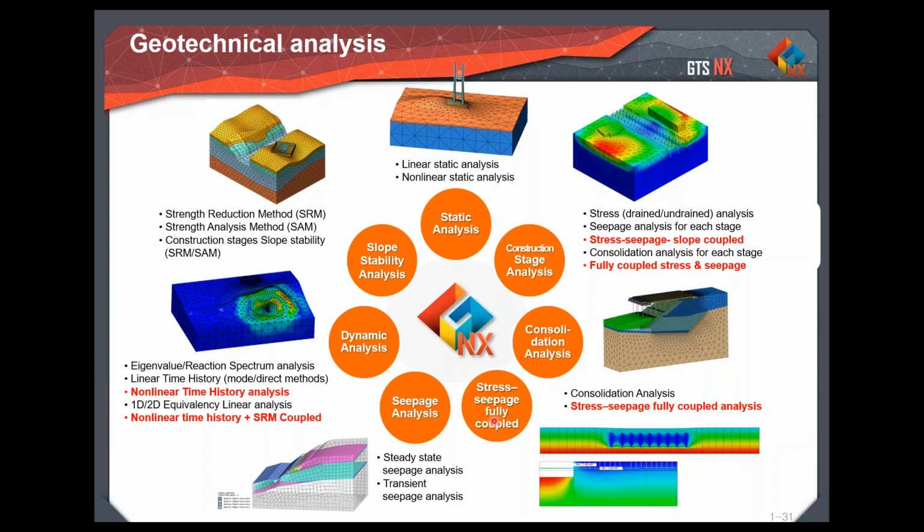Your factor of safety will be very low when compared with the factor of safety in dry conditions. That's what we can infer from the finite element method, and we need to run a stress seepage coupled analysis in order to get those particular results. And apart from this, we have a consolidation analysis. In this consolidation analysis, you can find results such as settlement with respect to time and pore water dissipation with respect to time. So you can find that in the consolidation analysis.